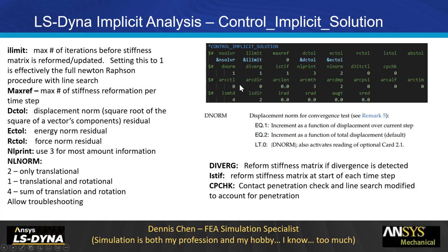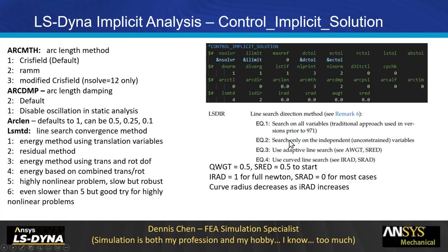Okay, that's a lot of information. Obviously the key here isn't to remember everything. The key here is to get the key points out, which are these 4 parameters, right? You're defining your solver, you're defining your tolerances for convergence. For everything else, look at the documentation as you go for each problem, which is the best way to look at it.